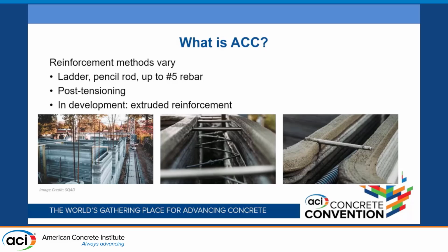As far as reinforcement, there's also a lot of different strategies here. Some folks are doing plain concrete, no reinforcement whatsoever. Some folks are using ladder, pencil rod, and rebar. You can see with all of the curves that can be introduced with this technology, and also the really thin bead size, people are getting creative. Traditional reinforcement is not so easy to install here. There's been research on post-tensioning, so actually printing the entire wall and then stressing strands at the end of construction. And there's also been research on printing the reinforcement as well as the material, so extruding some sort of cable or wire along with the concrete and doing it all at once.